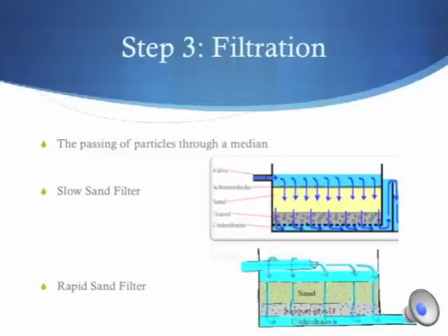The rapid sand filter is the most commonly used filter for surface water treatment. It is small and compact and cleans 2 to 3 gallons per minute per feet squared. Through straining and adsorption, the attraction of dissolved solids to other materials, even the smallest particles may be removed.